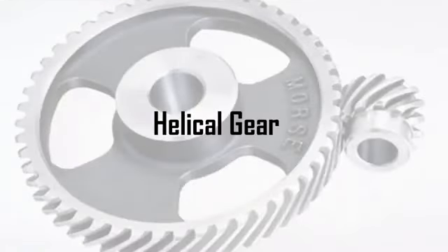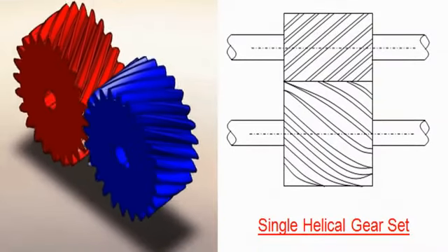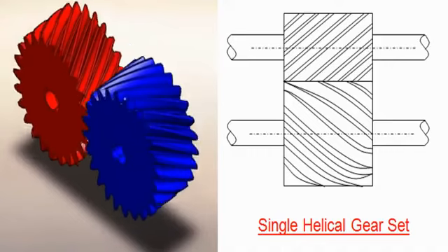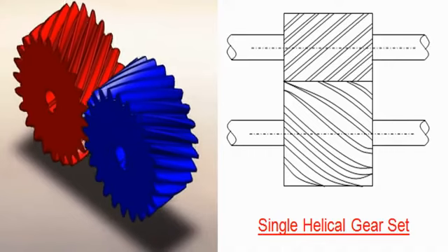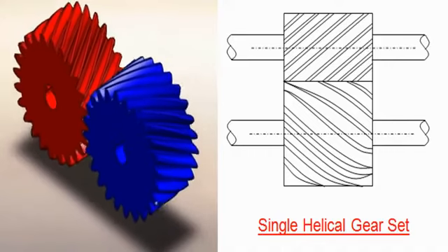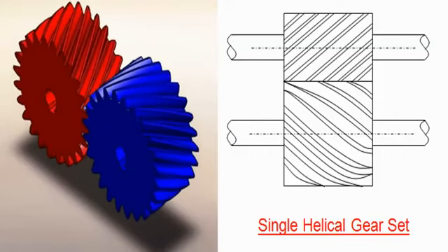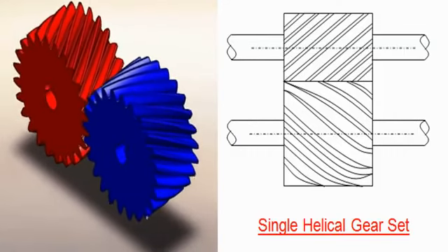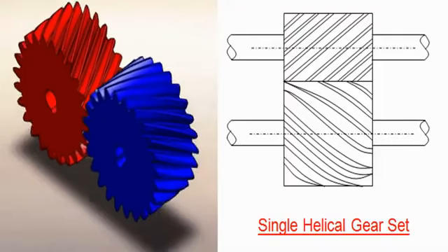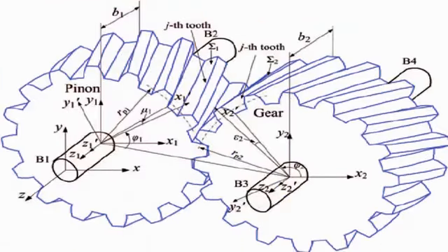Number 2. Helical gear. Helical gears are used with parallel shafts similar to spur gears and are cylindrical gears with winding tooth lines. They have better teeth meshing than spur gears and have superior quietness and can transmit higher loads, making them suitable for high-speed applications. When using helical gears, they create thrust force in the axial direction, necessitating the use of thrust bearings. Helical gears come with right hand and left hand twist requiring opposite hand gears for meshing pair.